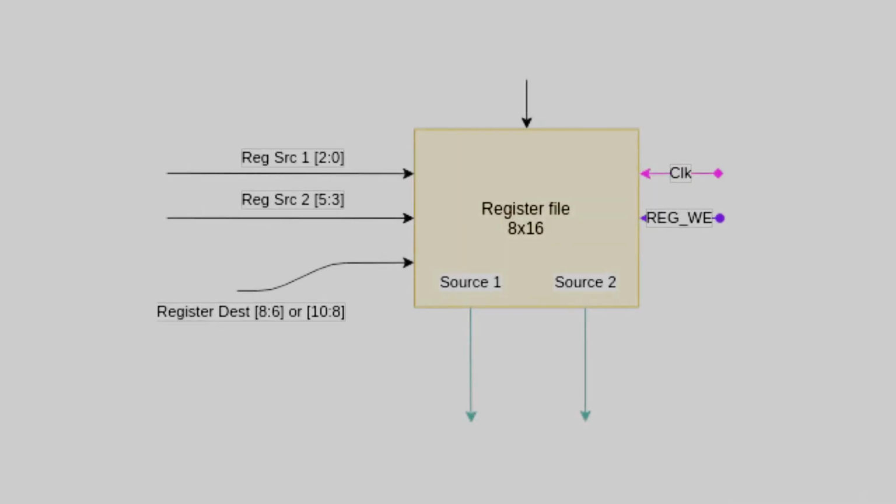Register files are similar to memory in that their instantiation is identical, yet they have triple address inputs and dual outputs. The two addresses specify source locations and the remaining one specifies the destination location. The data output is defined as asynchronous via a continuous assignment, which we learned in the previous episode negates any kind of inference of BRAM.